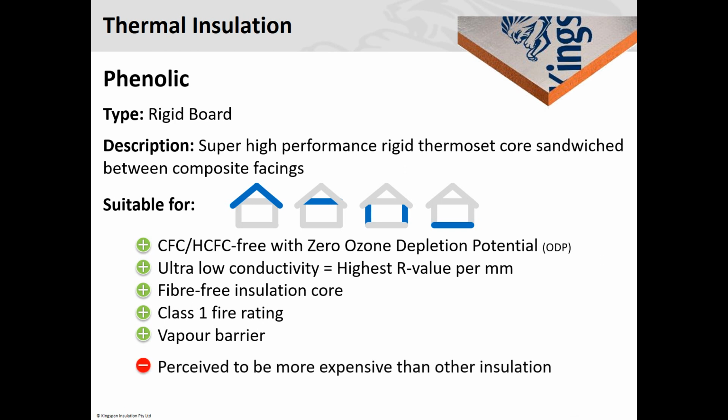So yeah, it's vapor membrane, then insulation, and then the chairs and your top bars, support and the top of your concrete reinforcement mesh. And then the concrete is poured. That way, as the underfloor heating is working, the heat's being forced up, and you've got an insulation layer between the earth and the concrete.